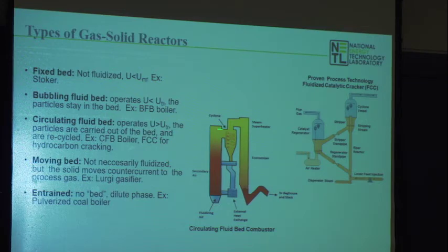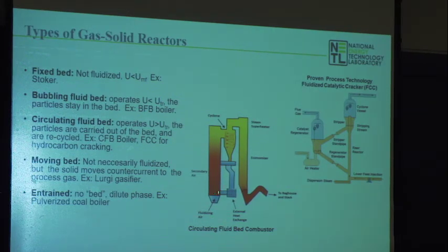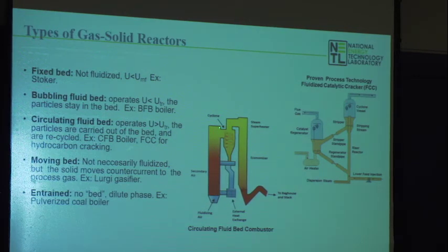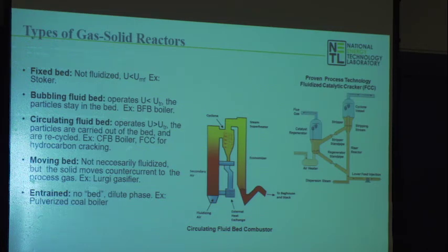Probably more commonly in a little bit wider use, circulating fluid bed reactors. Here you put in fluidizing air in this region of the combustor. There's a fluidization region here that's turbulent, and then you convect up into this region and then go through this cyclone, and the material just circulates around here. Most of that circulating material is bed material, not coal. I said before, like 2% of it might be coal. And so the rest of that material gives you nice uniform temperature all the way around while you're operating the system. It's a big thermal mass circulating through that system.